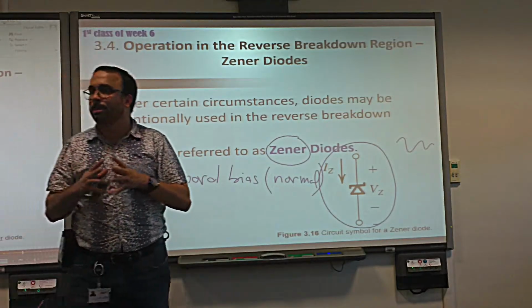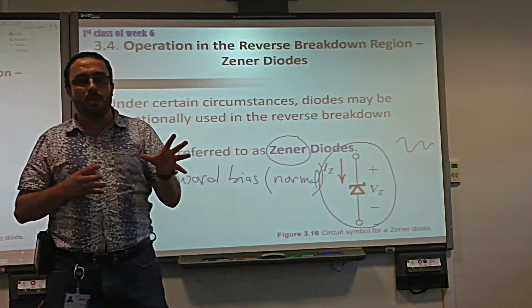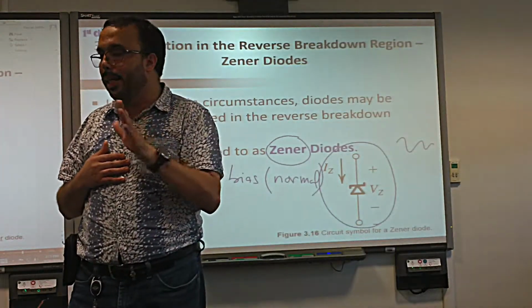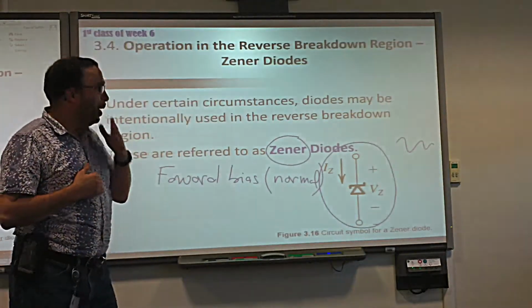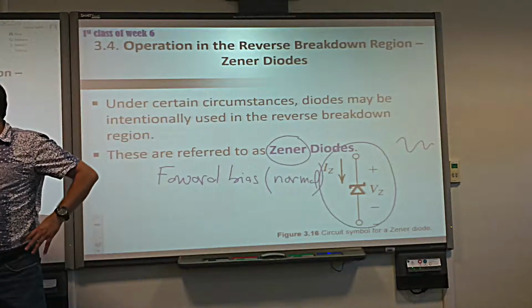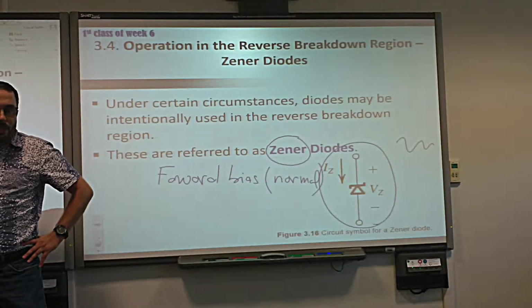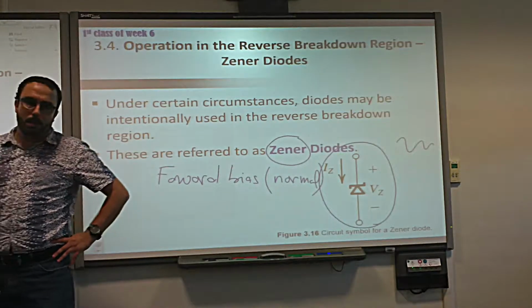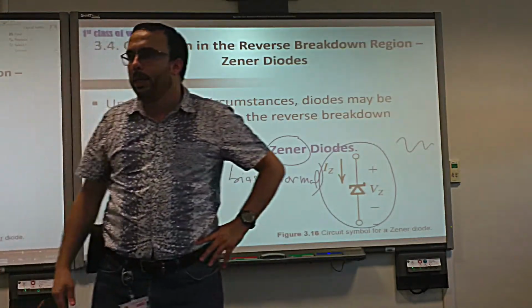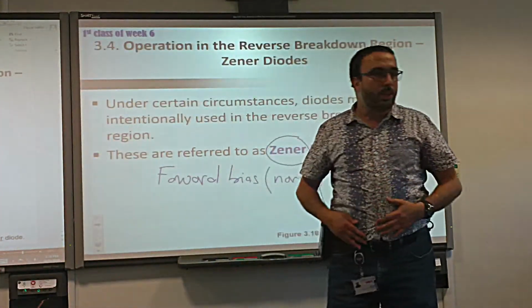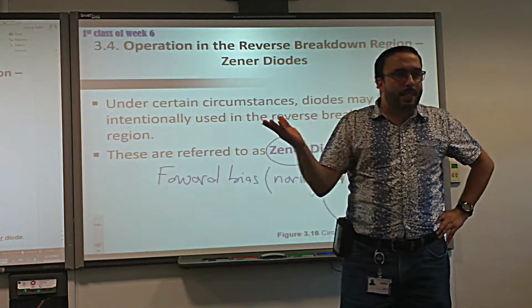Very good. So these are the 2 zones of the real diode, not the ideal diode. The model of the reverse zone is simple: it is an open circuit. The current is very small, so you can assume that it's an open circuit.